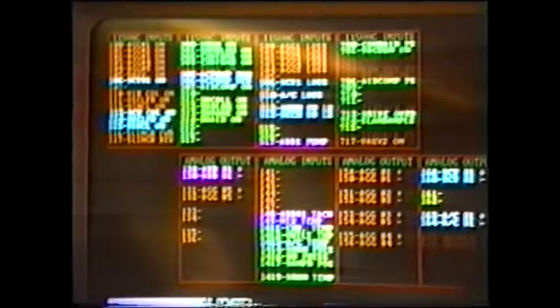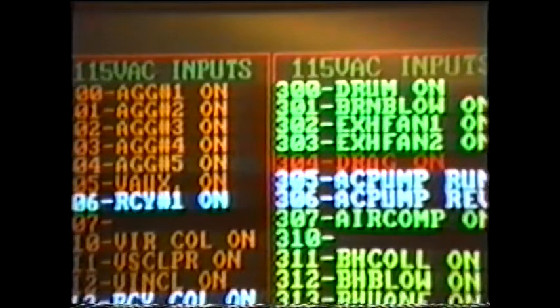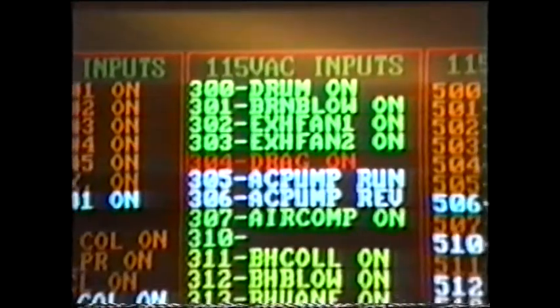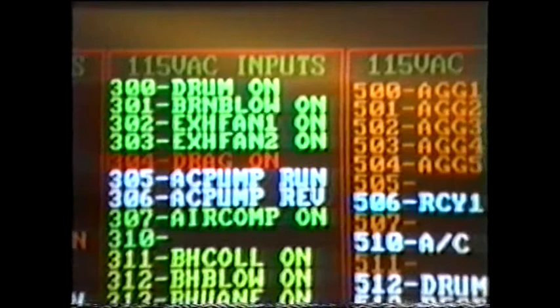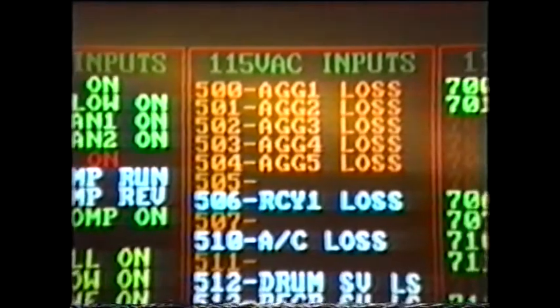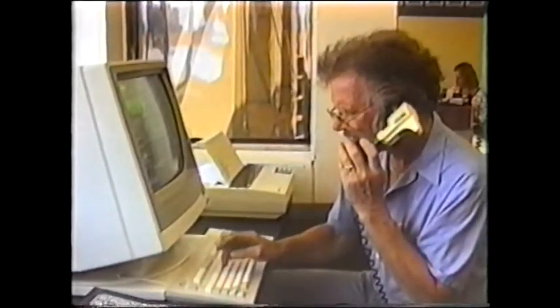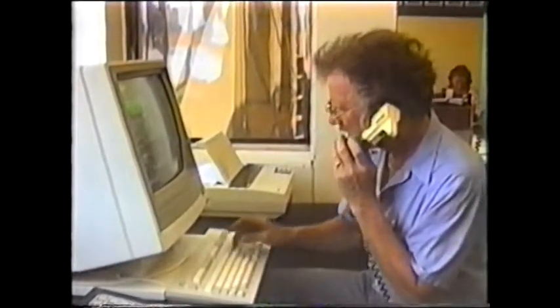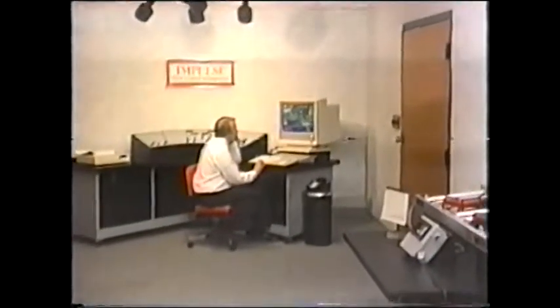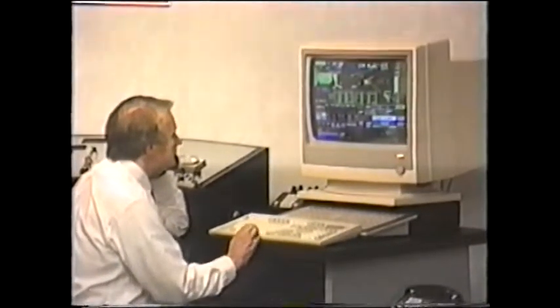Another diagnostic tool lists input-output devices in the programmable controller. This feature reduces operator time previously spent looking up schematic drawings to get wiring information. He can bring up individual screens and see exactly how the plant input-output rack is laid out. With the optional telephone modem, personnel at CMI can access any plant and see various screens just like the plant operator without interfering with production. It's a very quick way to get help directly from the factory in isolating malfunctions and finding solutions to them.